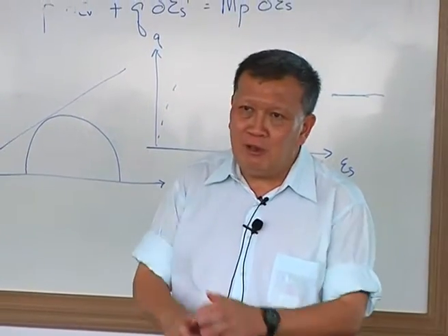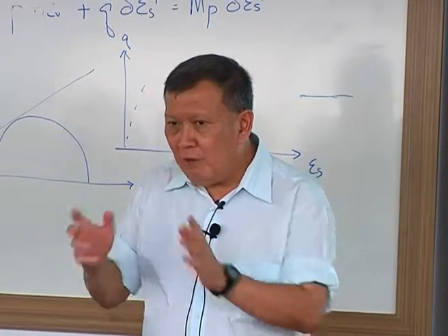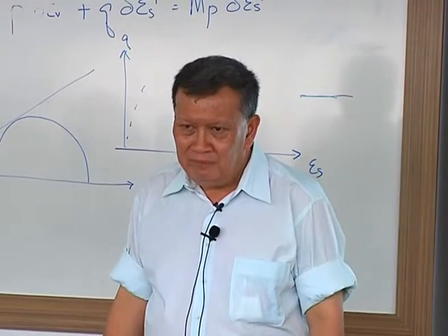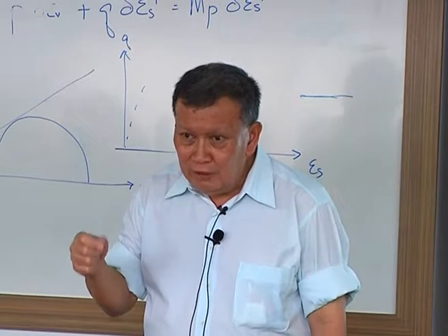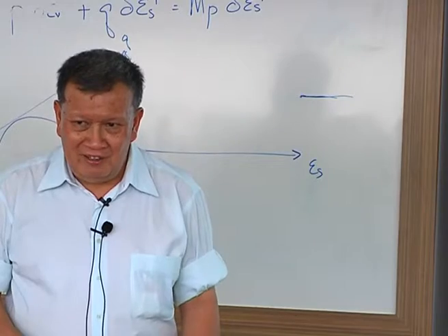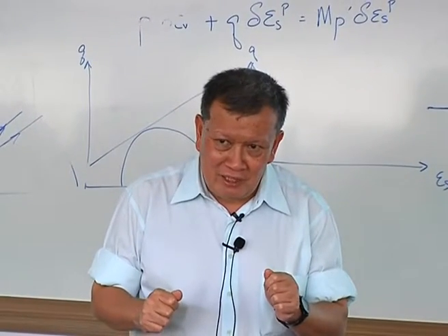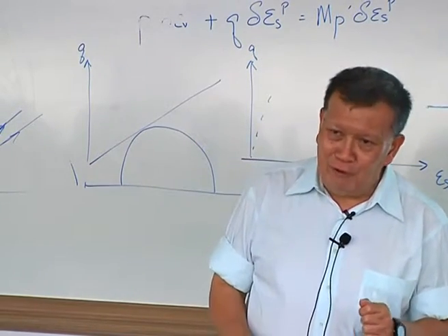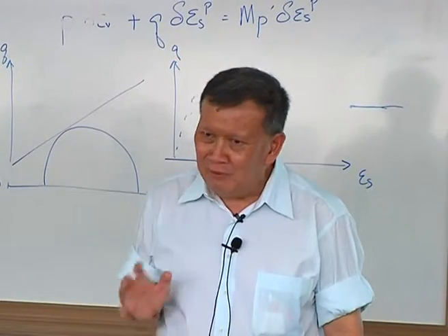Fort Canning, I just model it as a Mohr-Coulomb because, okay, one thing you need to do in a finite element study is to do a parametric study. If the problem shows itself to be very sensitive to the stiffness, then you know that it is actually a fairly safe problem because you know that it's controlled by modulus. If it is not sensitive to stiffness but sensitive to strength, then you know that you have a very low factor of safety. It's almost like you're on the tail end, so you've got to be careful with that.